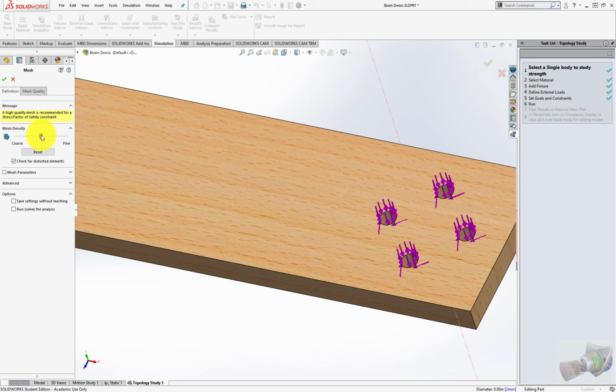So this is definitely one of those situations where it's an iterative operation. We may have to go through 100 simulations, we may have to go through 1,000 simulations to get there. My point is, if you make your mesh really fine, this is going to take a really, really long time to solve. So I just previously did a topology optimization simulation. It was going to take about 24 hours because I set a really fine mesh. So I decided that was probably too fine, and we backed it off a little bit, and we made it a little bit more coarse, and it took a lot less time.